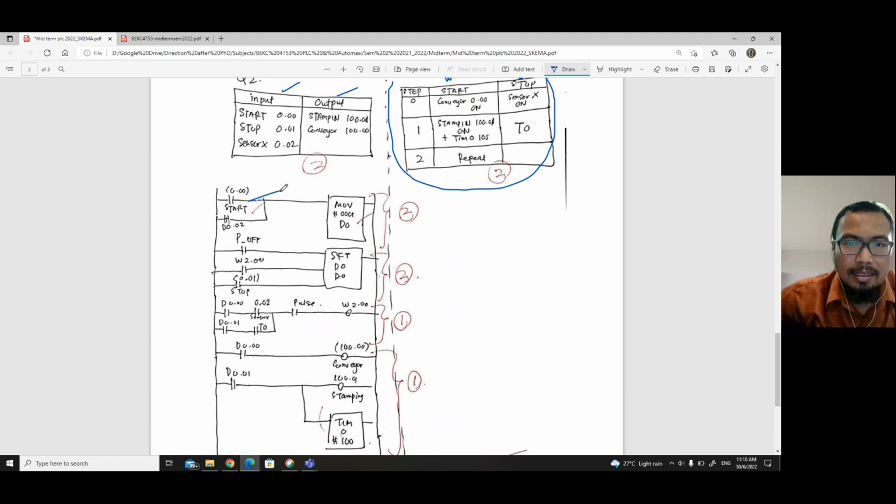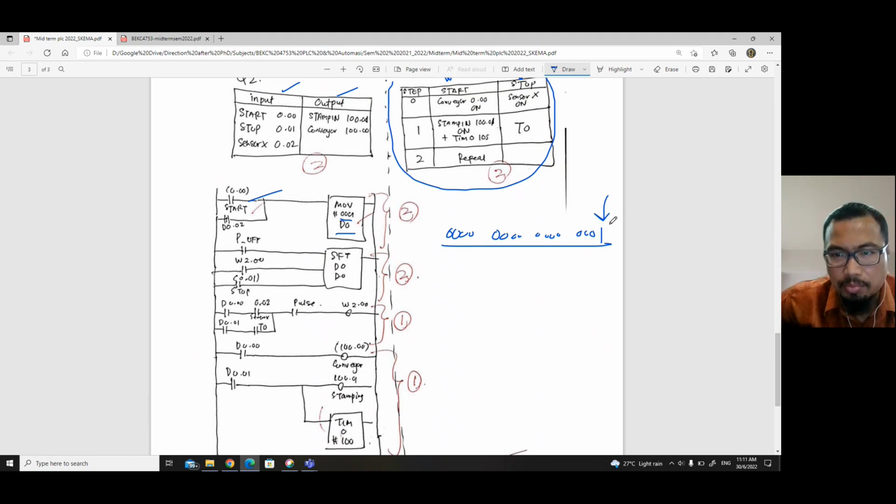Usually we have the start here because I want to move the value of 0001, which means 0000 0000 0000 0001, into register D0. Here, in this case, I use D0. Why? Because I want bit number 1, the first bit, to be on 1. Then the next rung is the shift register rung, the shift register block, SFT D0 D0.